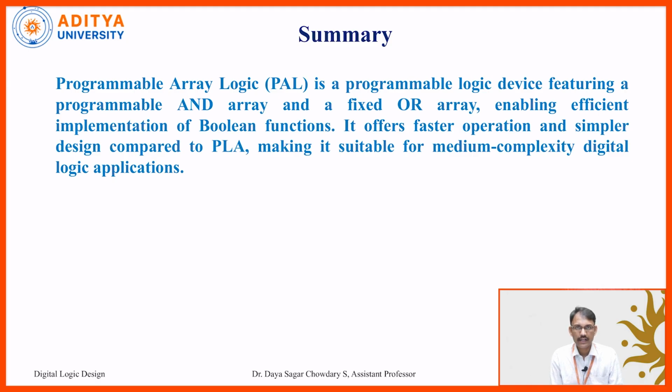And coming to the summary, programmable array logic, which we simply call PAL, is a programmable logic device featuring a programmable AND array and a fixed OR array, enabling efficient implementation of Boolean functions. It offers faster operation and simpler design compared to PLA, making it suitable for medium complexity digital logic applications.